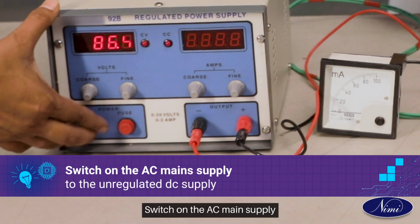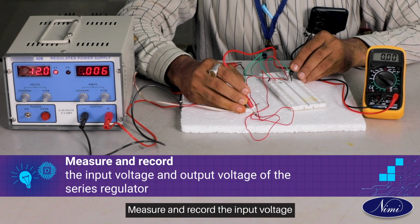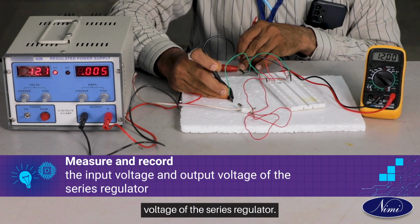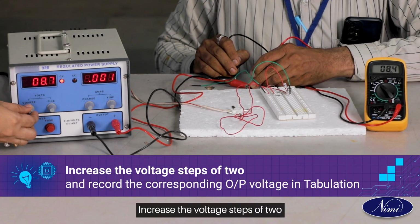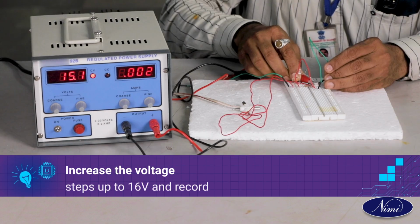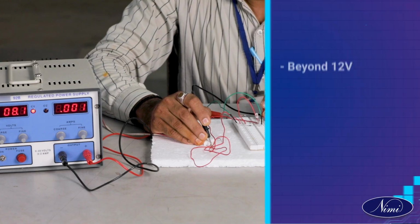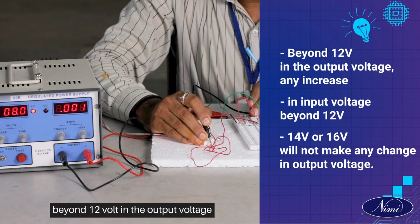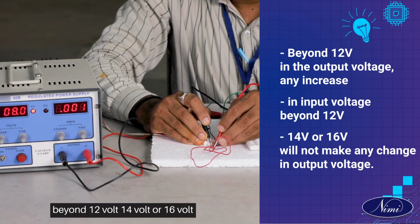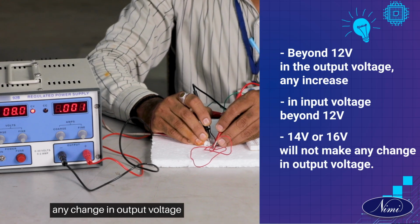Switch on the AC mains supply to the unregulated DC supply. Measure and record the input voltage and output voltage of the series regulator. Increase the voltage in steps of 2 volts and record the corresponding output voltage in tabulation. Increase the voltage steps up to 16 volt and record. Beyond 12 volt in the output voltage, any increase in input voltage to 14 volt or 16 volt will not make any change in output voltage.